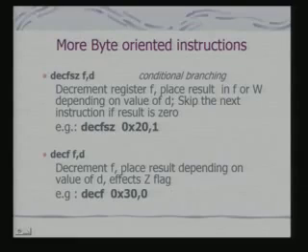The next instruction which has been fetched cannot be executed. So that instruction has to be replaced by a NOP or no operation. So effectively this instruction would require now 2 cycles for execution. That is, when the result is 0, this instruction will actually require 2 cycles for execution and not just 1 cycle for execution.